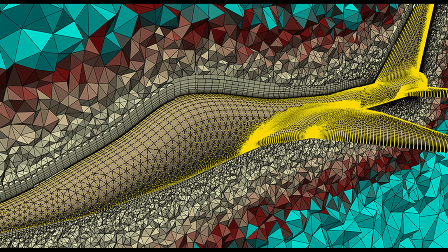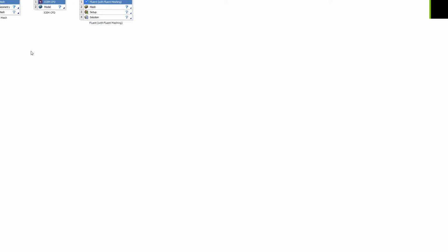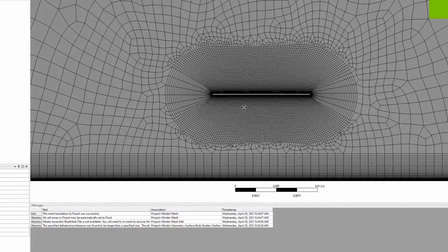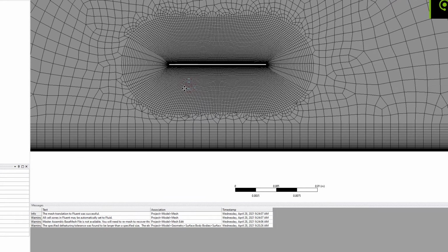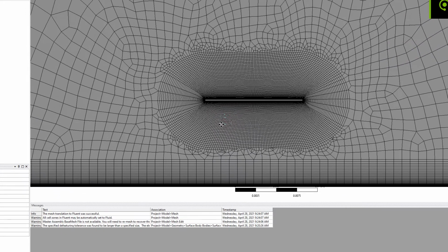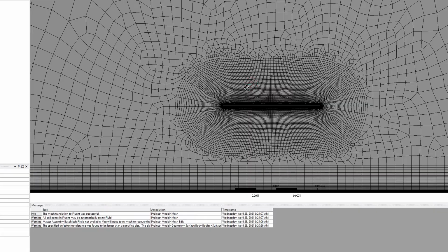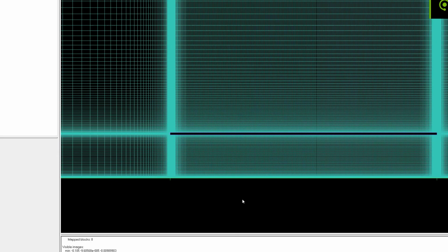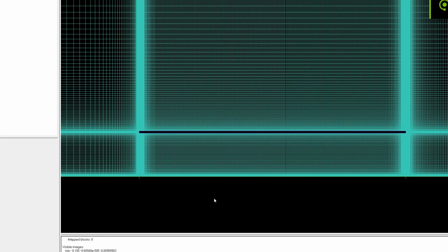For these solvers to work, however, the user must input what is called a mesh. Mesh is a group of control volumes, which gives the solver locations at which to either solve or model the governing equations. ANSYS has several software options available, which let the user turn geometry into a mesh, including ANSYS Meshing, ICEM Mesher, and Fluent's built-in Mesher. ANSYS Meshing is mostly automated, allowing the user minimal control over the mesh parameters but taking little time, whilst ICEM Mesher requires the user to create the mesh, allowing more control but taking significantly more time.